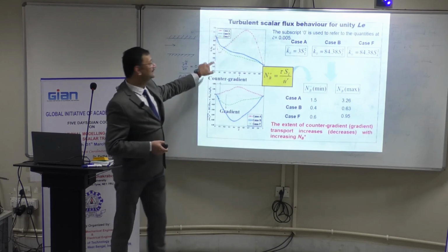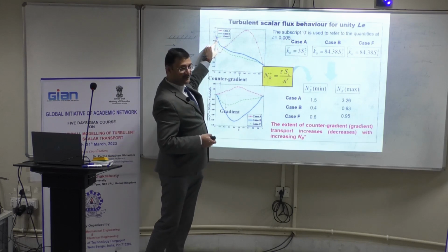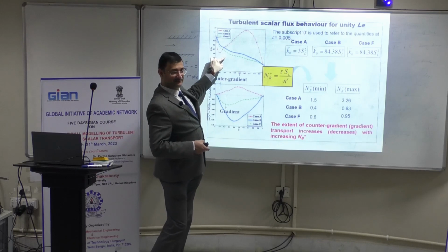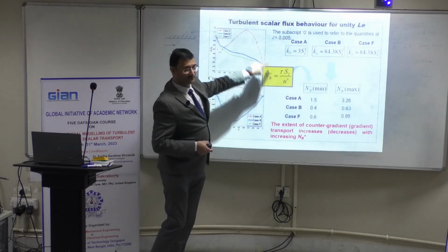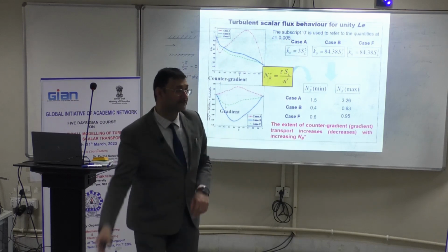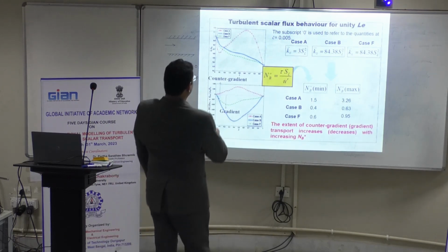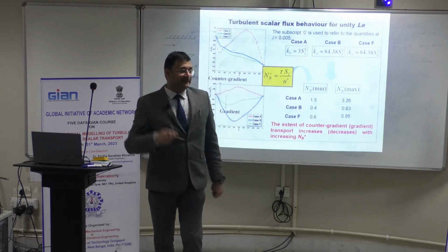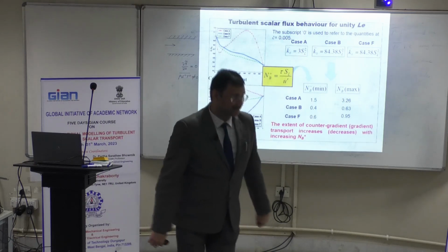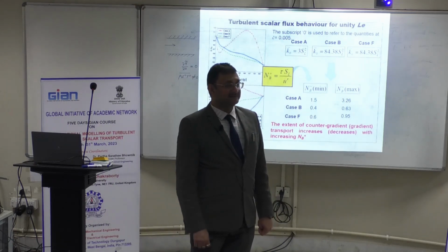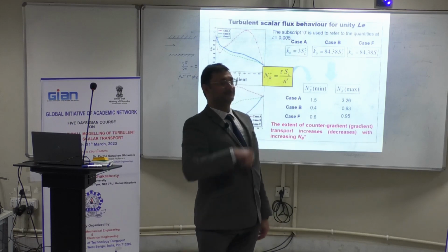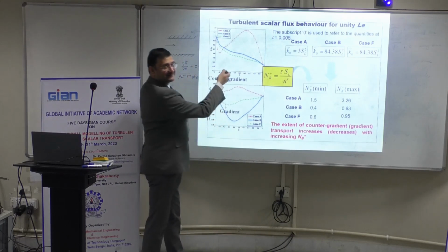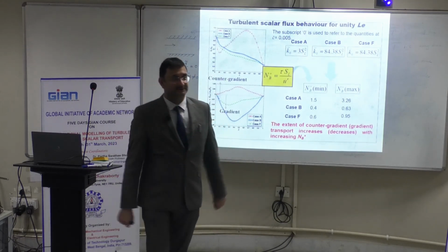Okay? And that's why the turbulent kinetic energy from the unburned gas side was the case. But as the heat release effects become strong, it shows considerable increase before it goes down towards the burned gas side. In other cases, the thing is there, but turbulent kinetic energy decays because kinematic viscosity goes up with the increase in temperature, and that basically damps the turbulent kinetic energy. So that's the reason eventually it drops, but this increase is because of the strong thermal expansion effect.